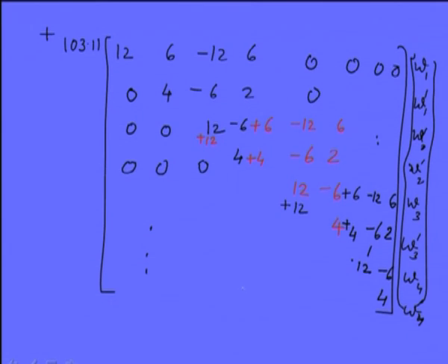So this is the stiffness matrix, and the previous was the mass matrix. This is equal to the internal forces, that is minus S1, M1, then S2, M2. This is coming from the first element. From the second element, these are the entries.